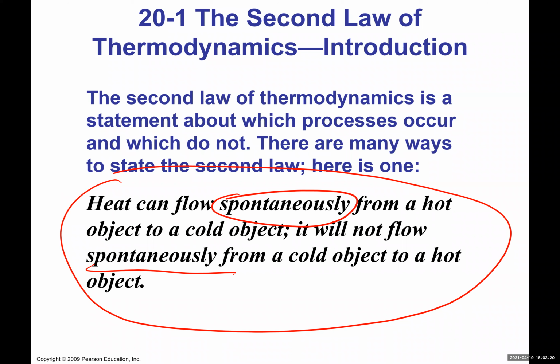One of the ways we can describe the second law is that it gives us direction, in which direction the heat is flowing. And it's a law. That means we can take that as given and assume that heat will go from hot to cold, but it will not go from cold to hot. That's a very important implication. Whenever you are designing something like a heat engine or a refrigerator, you have to take this into account. Some things you can do, some things you can't.